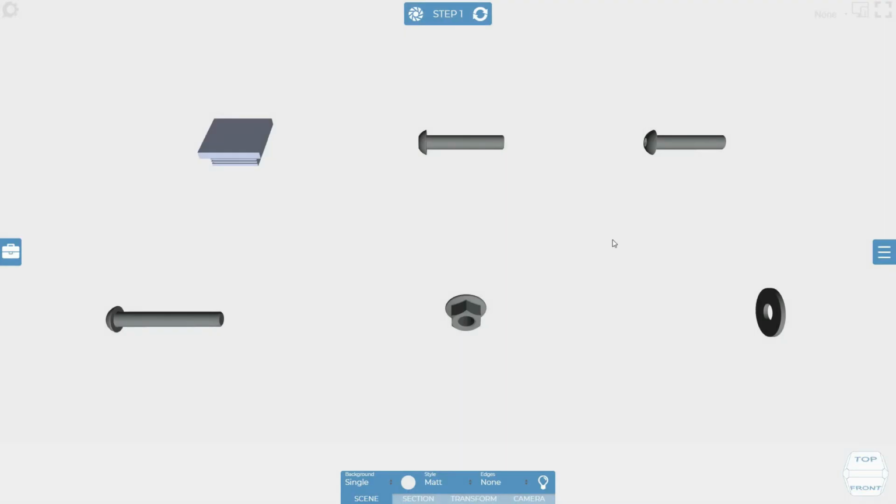As a little tip, rather than me placing on labels and linking them constantly and having to do that in this case 6 times, if I'd saved a toolbox item with a link already in it into our toolbox, then every time I add that, it'll automatically pick up the linked property. And actually, the balloon that comes in the default toolbox automatically links to the item number.